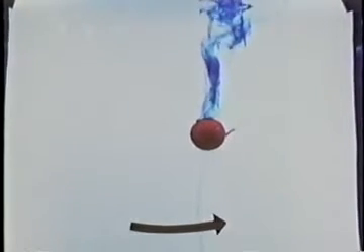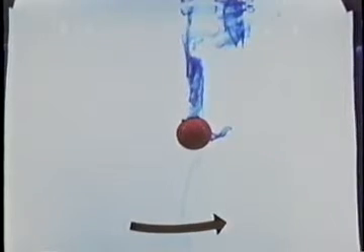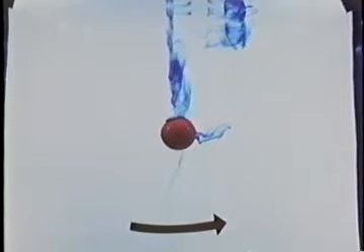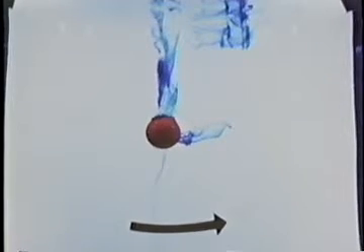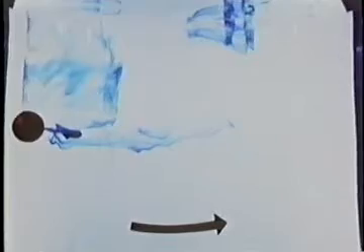We increase the towing speed. At this high Rossby number, the motion becomes three-dimensional and the Taylor column is left behind. Here's the same motion seen from above. When the ball is accelerated, it swerves to the right, like the earlier vortex ring.